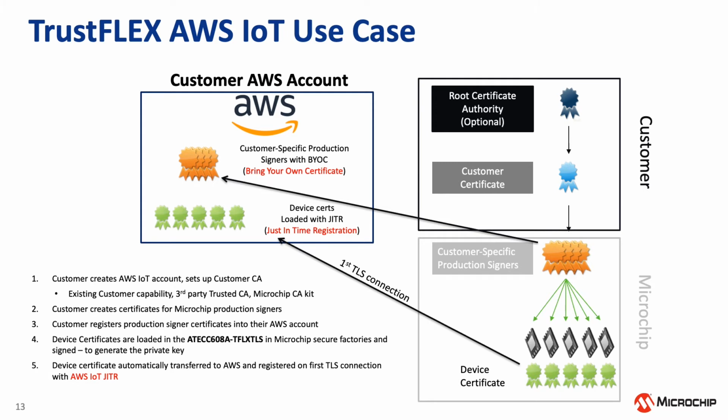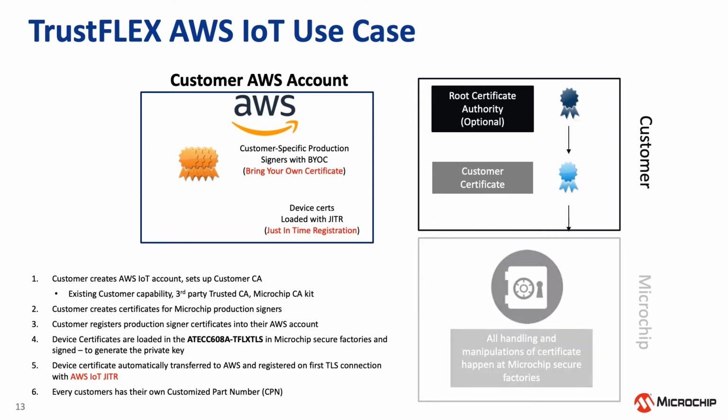You will give this customized secure element to the CM that doesn't have to deal with keys. So from a security standpoint, it is isolated from the keys. And from a logistics standpoint, just grab a part, solder it, and the code on the microcontroller is always the same. Very efficient. At the end, the customer has a customized part number, and that's how the device itself is attributed to the customer in a unique manner.